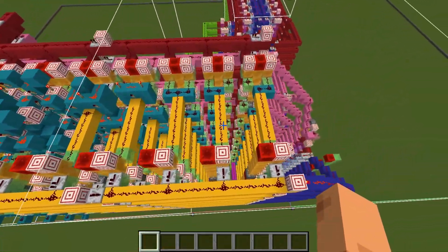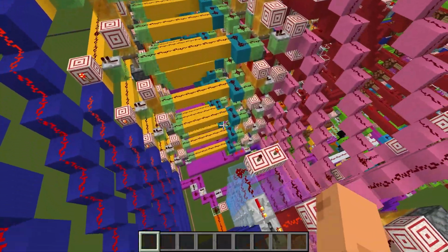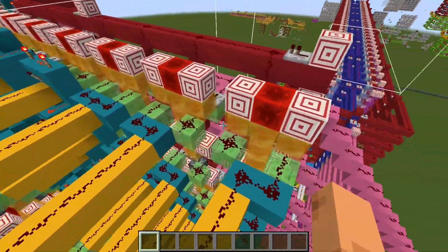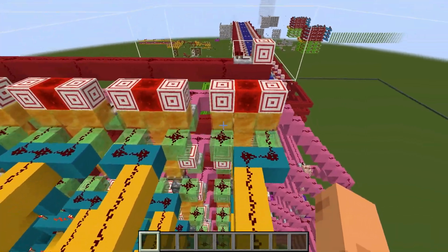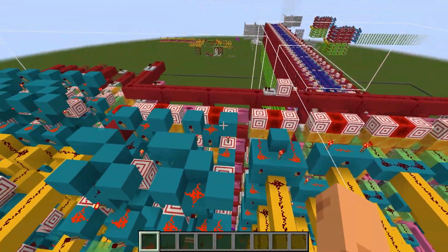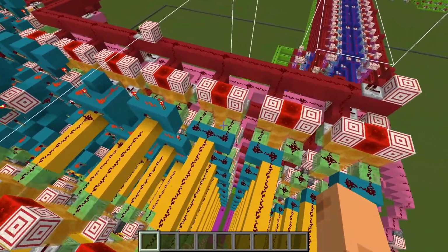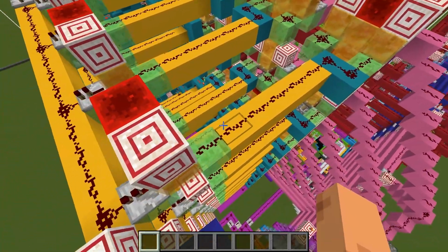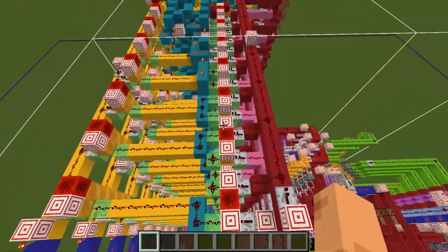If we just look at the very top slice, because all these things are repeated basically vertically, we have 8 instances of the same logic function stacked on top of each other. If we just look at the top layer, we have 1, 2, 3, 4, 5, 6, 7 functions basically. I know these are functions because they take 2 inputs and output 1 output. So in general, this ALU operates on 2 data inputs.